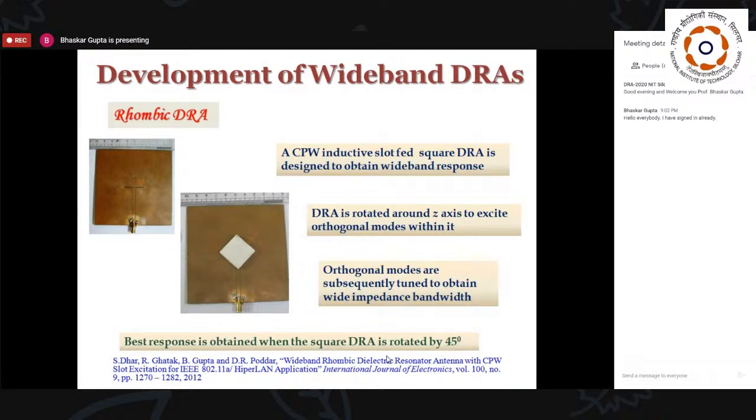It can actually be modeled as another equivalent structure, double the height, by removing the ground plane, that is considering the antenna along with its image. So you see the structure, and now look here at the basis of design of this structure.